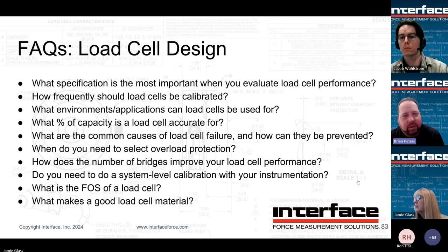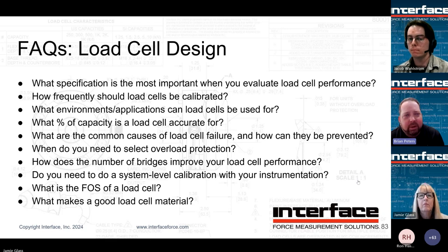If you're more concerned with the torsional bridge, then you'd want to start with one of our 5600s, which begins life as a 5400 reaction torque flange sensor, and then we add axial bridges to it. Typically the best thing to do if you're very concerned about crosstalk is to characterize it: do some applied loading, see how it impacts the signal, and then adjust for it in your instrumentation.